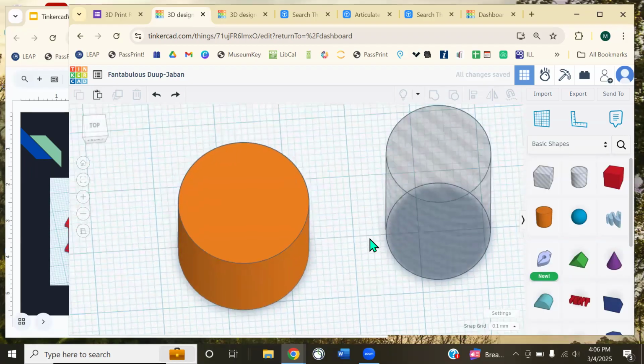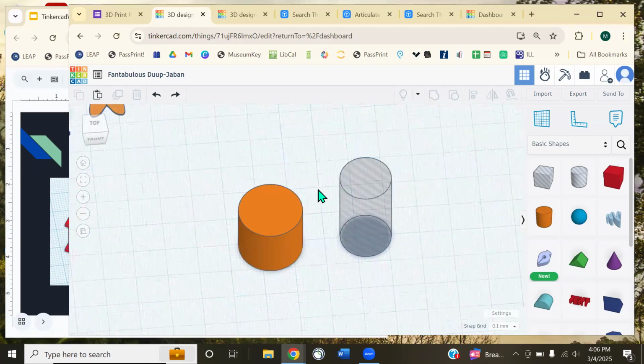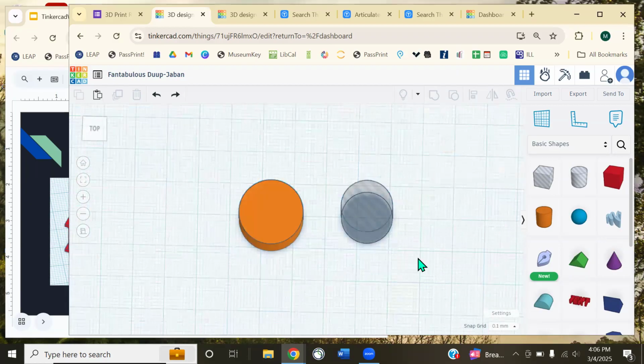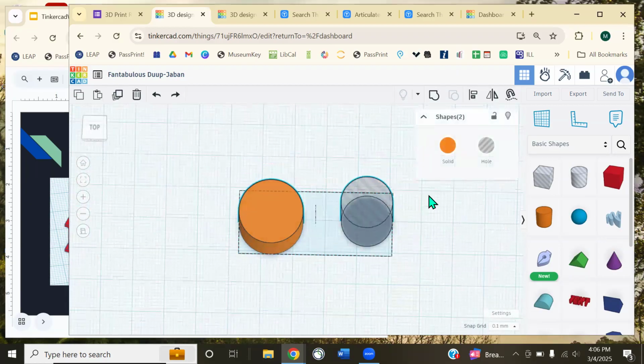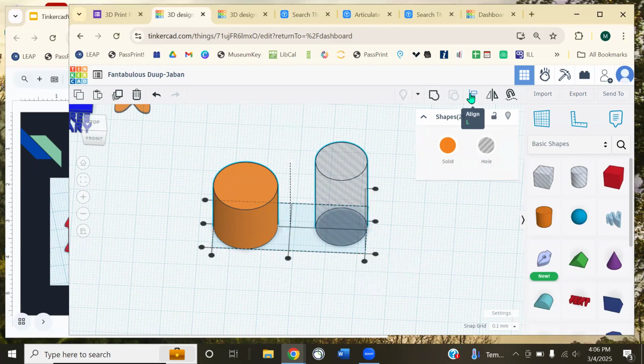The most useful thing we'll do actually is use the automatic alignment tools built into this so everything's exact and up to snuff that way. I'm going to left click, drag, and select both of my objects. I have them like this. And then up this way, we have the align tool. So I can click on that. I can also just tap L to get it activated. And then you can see we have all these little buttons pop up.